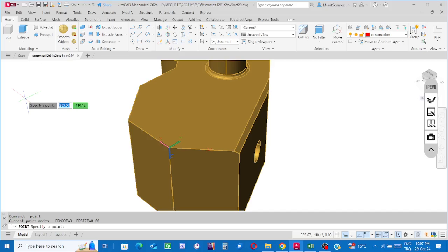You see, in this method we know the location dimensions with respect to the corner. These are given along the edge. Along the second edge, the distance from the point to the origin is say 70. Okay, click on the comma key. Ordinate is 0. Altitude is 0.